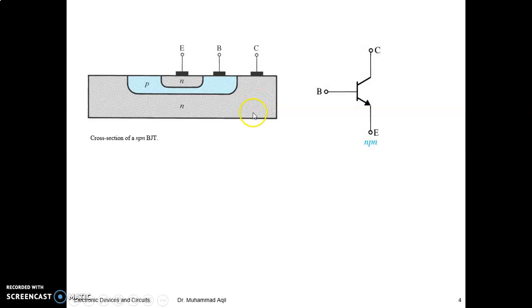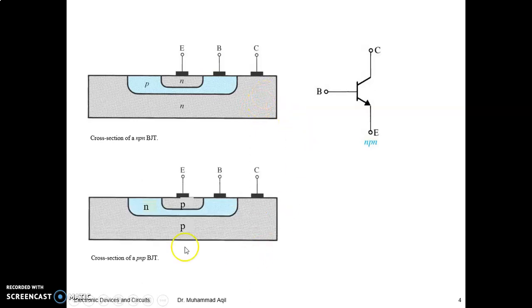And very moderately doped. So the same would be the case in a PNP transistor, because you have to make this junction forward biased, and because the emitter here is P and the base here is N, the emitter should be higher than the base, and to make this reverse biased, the base should be higher than the collector. So our emitter would be at the top of the page, base in the middle, and collector at the bottom, which is in contrast to the NPN transistor, right?